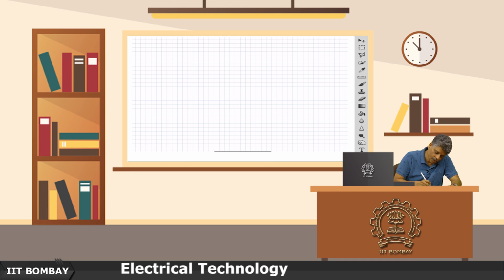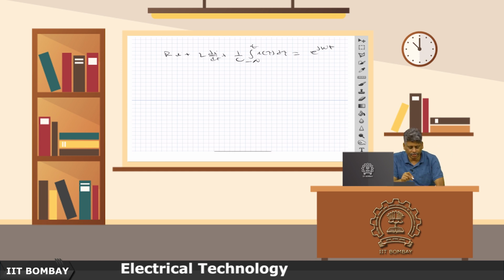So, let us now say that my excitation function is e to the power j omega t, and I want to solve the circuit R times i plus L di by dt plus 1 by C integral of i dt when it is excited by e to the power j omega t. Suppose I want to get the steady state response to this function. So, what I will now do is first of all assume that